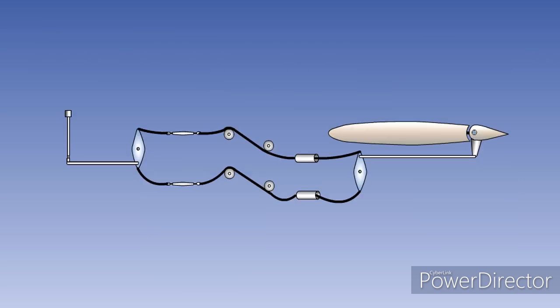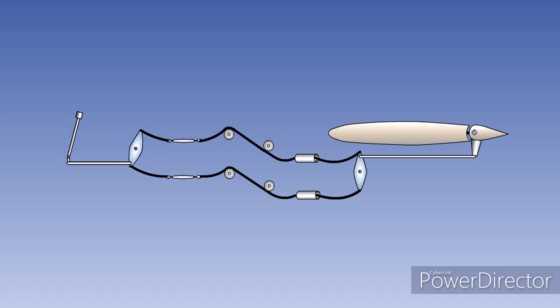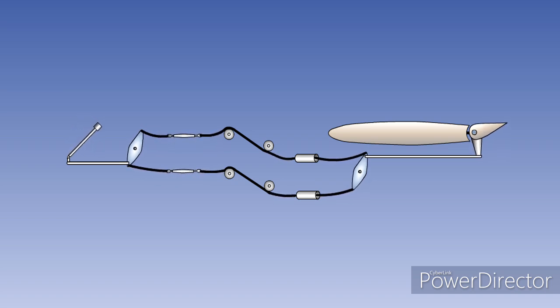Control systems should be free of backlash. Backlash is free or ineffective movement of the cockpit control when the direction of movement is reversed. It may indicate worn or incorrectly adjusted components in the control system. Excessive backlash can exacerbate the problem of control surface flutter. As you can see in the extreme example shown here, the column has to be moved a considerable distance before there is any reaction from the flight control surface.